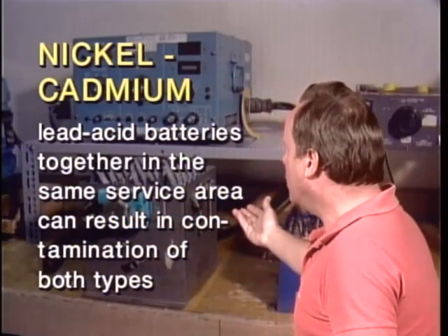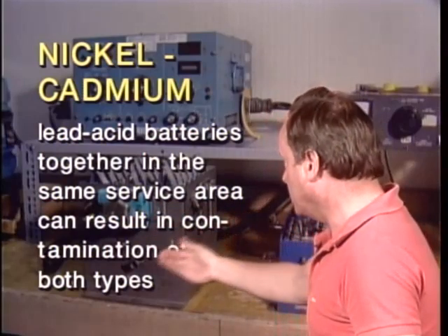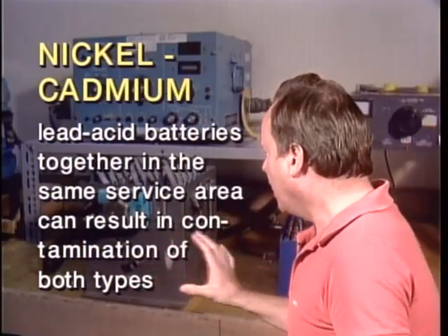All right, now, should you ever service NiCad and lead-acid batteries together in the same service area? And the answer is no, you should not, because it can result in contamination of both types of batteries because the fumes are not compatible with each other.